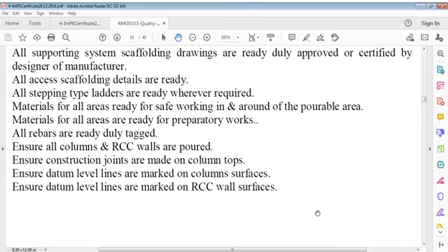When you do column full height, you can't do full height because of certain connecting bars to beams that may be placed on top of the column in the shape of a 7, or you can say L. Those L bars may be fixed on top and what to do, just cast columns below that bar so that dowels are not required to be placed in, and at that level somewhere near the bottom or soffits of beams we lay.